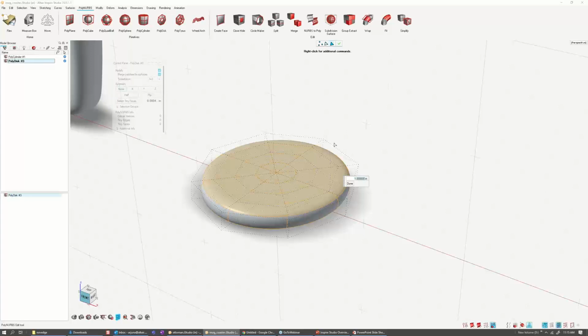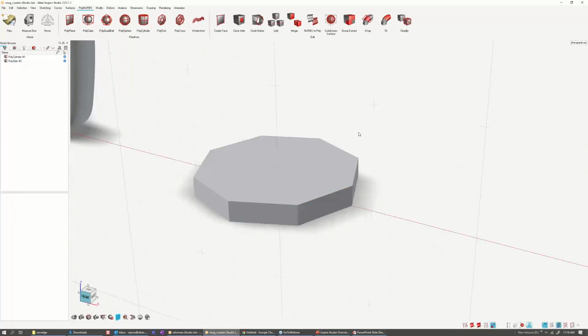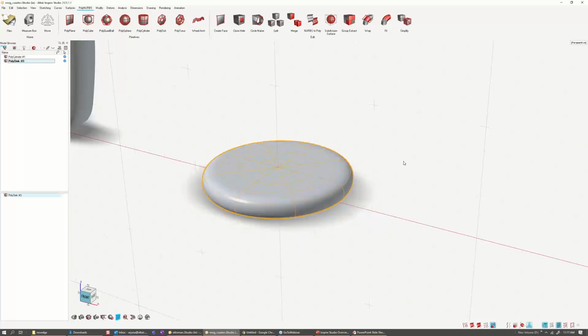I mean, it's a smoothened version of a mesh that is underlying. To actually look at how the mesh is laid out, you can hit N on the keyboard, and this is what it looks like underneath. So I have created a disk and extruded it, and this is what it looks like. But when I hit N on the keyboard, I can toggle between these two views.